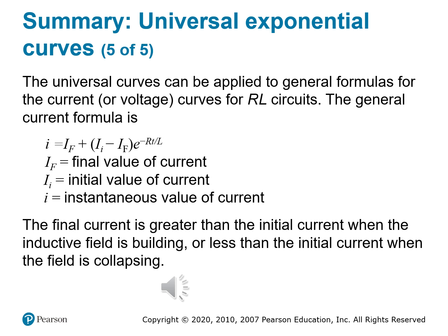And the factor e raised to the negative Rt over L is the exponential term tied to the circuit's time constant. What does this formula do? It blends the starting and ending points of a current transition. It's based on how much time has passed and the circuit's L to R ratio. So you get a precise current value using this formula instead of an approximation on the graph. You can use this for rise behavior when the inductor is energizing, decay behavior when the field is collapsing, or switching conditions in digital loads, motor wind down, or solenoid release.